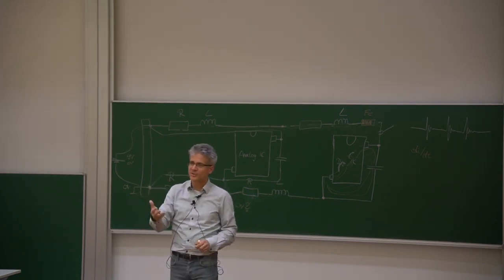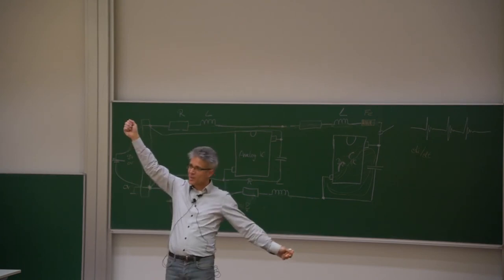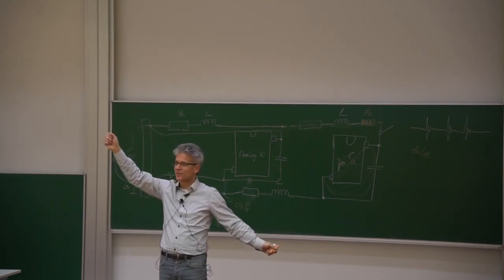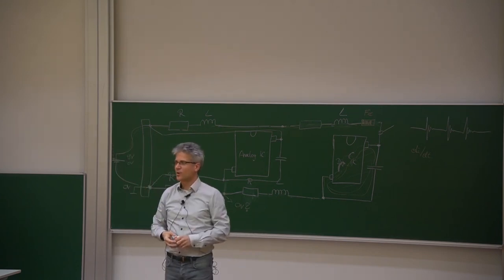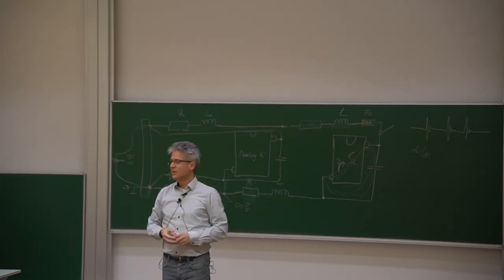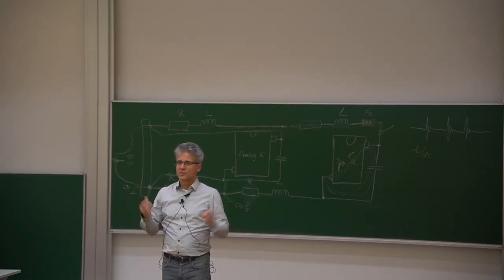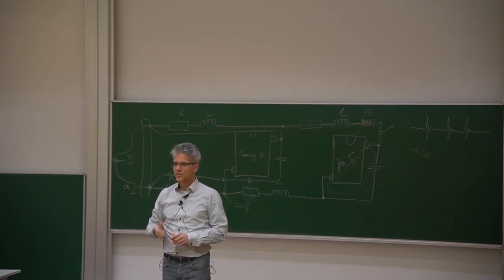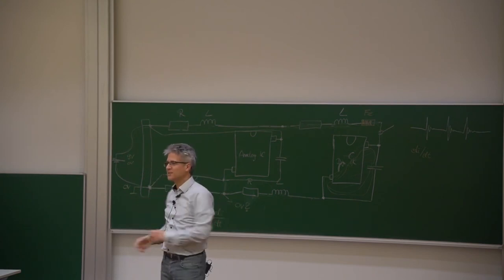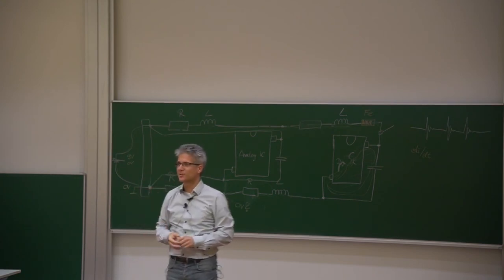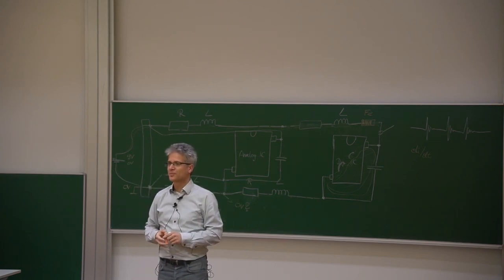Also, I hope you agree that this gives the biggest loop area, the biggest parasitic inductance, the longest bond wires, the biggest inductances of the bond wires, and the biggest voltage drops across the bond wires, and the biggest ground bouncing and VDD bouncing. So from the EMC perspective, nobody would do that. But it started in the 1960s, 70s, and maybe they didn't think about EMC during these days. Okay, it's a good excuse.